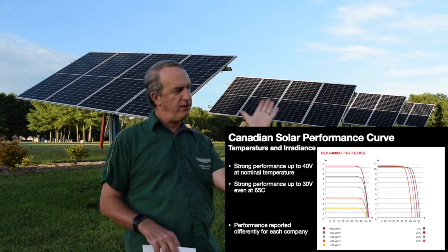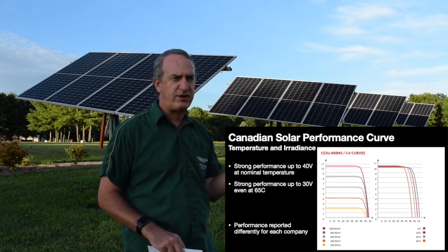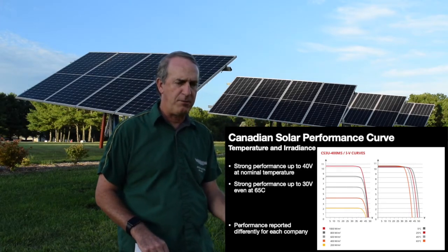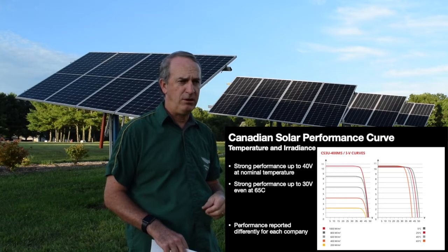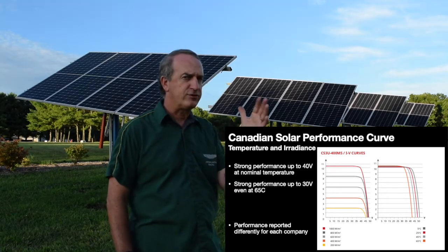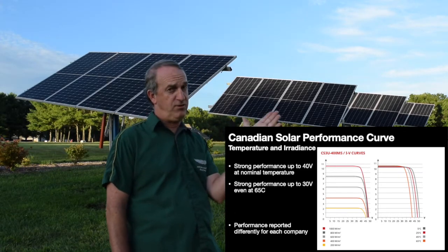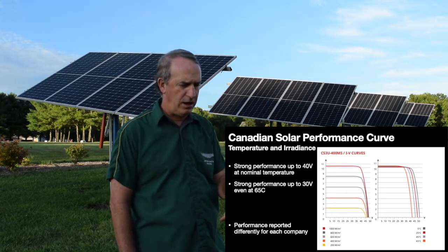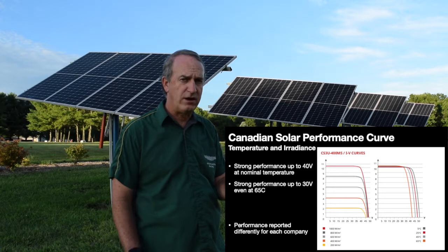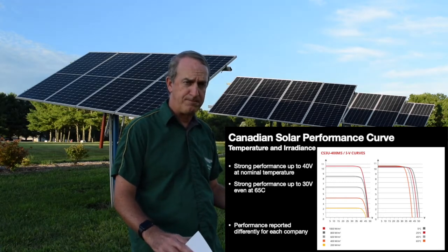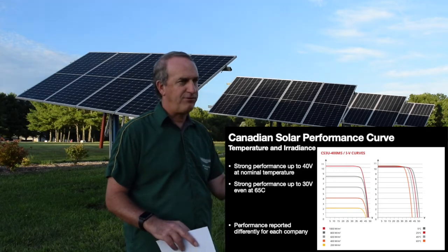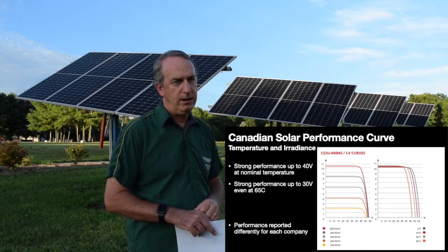When the sun is off angle, and we talked about that in the second video, you use the cosine to figure out how much direct energy is hitting the panel, and you're not going to get 1,000 watts of irradiance. If it's at a 45-degree angle, as we said in the second video, then it's going to hit at 707 watts of irradiance per square meter. So that's 70%.